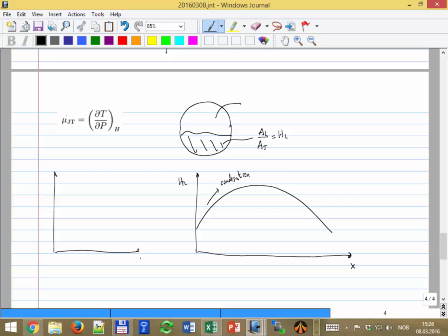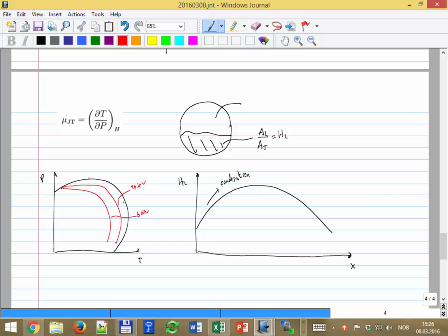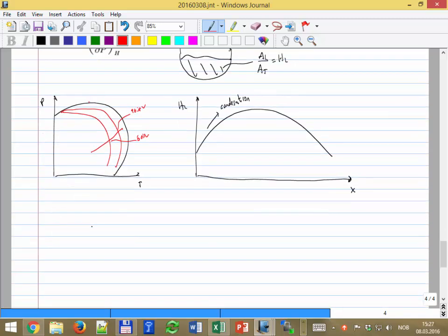And remember in the phase envelope, we have something called quality lines. You remember that? Yeah, from your old course. Here you have actually 90% vapor, and here you have 80% vapor. Quality lines, equal quality lines. So if the point that I'm analyzing in the pipe goes in this direction, it means that all the time the liquid fraction is going to increase. Do all of you know what quality is, or remember what quality is?